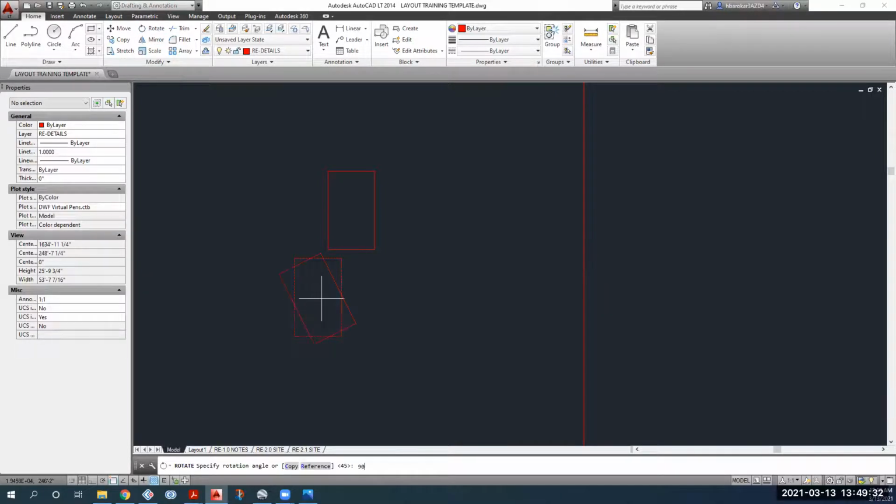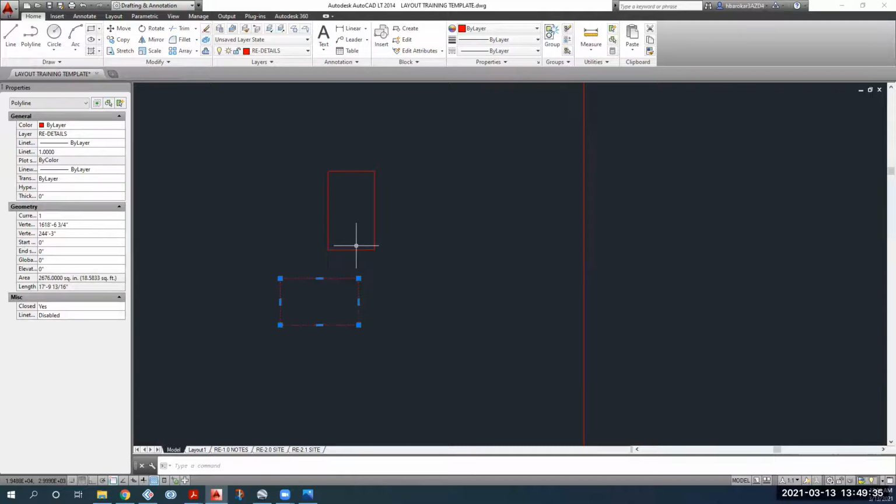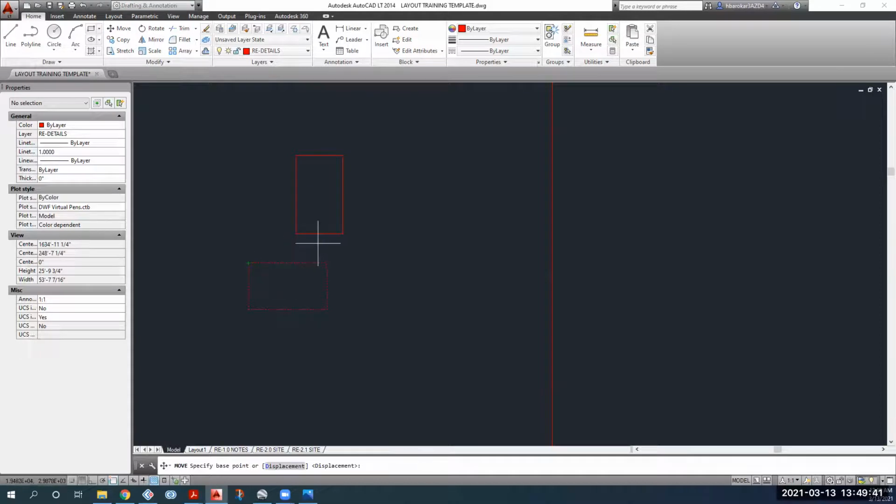Remember, this is still flat. We still haven't projected this. Now we're going to set up the rig to project it. But before that, we are going to put a distance or gap between this panel and this panel. And that gap always has to be 3/8 of an inch. The reason we have that gap is because that is where our braces fit into those modules, and the thickness of those braces is 3/8 of an inch.